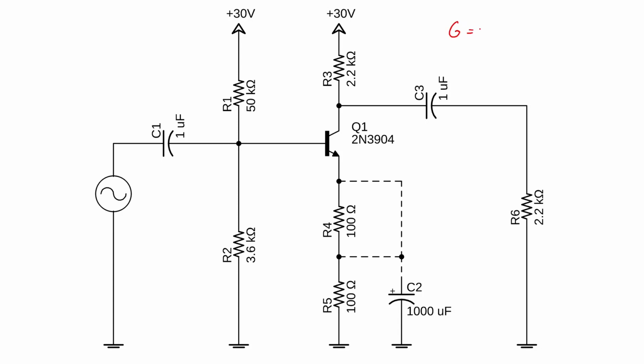So gain is V out divided by V in. For this circuit, gain will be the resistance in the collector divided by the resistance in the emitter circuit. When we say resistance in the collector, what we need to do is think about it from this standpoint right here. So if you were looking out from the collector, you would see this 2.2K resistor, and you would also see this 2.2K resistor.